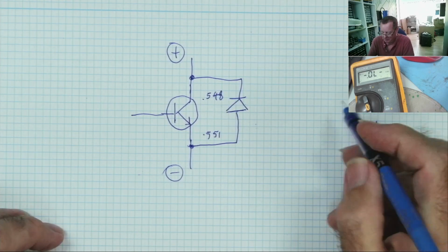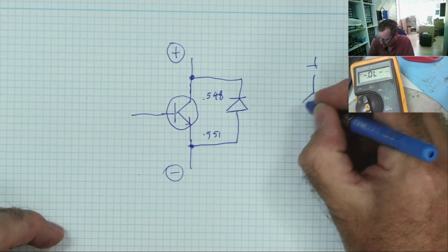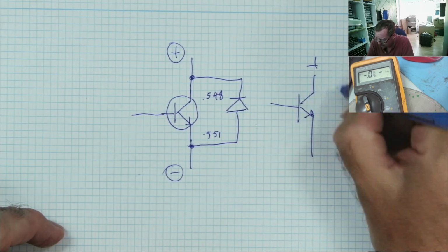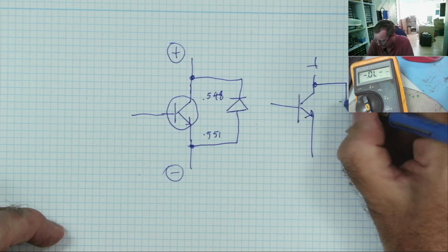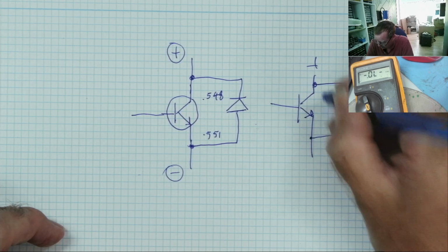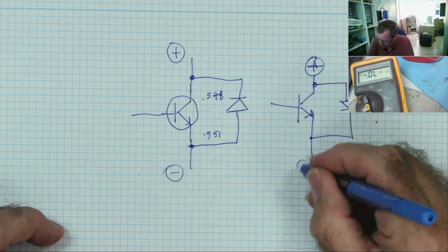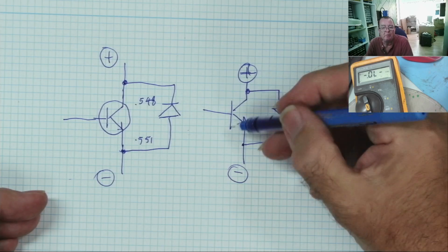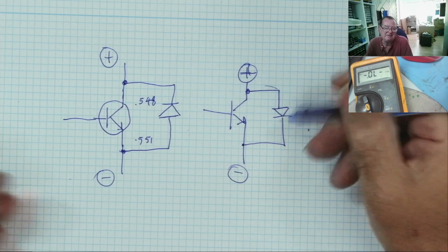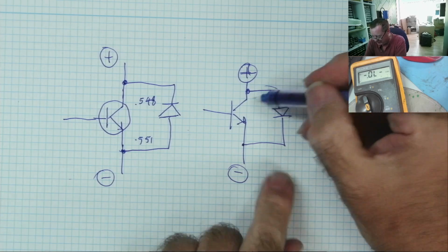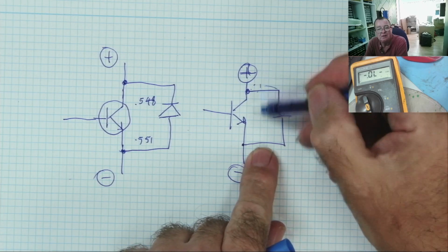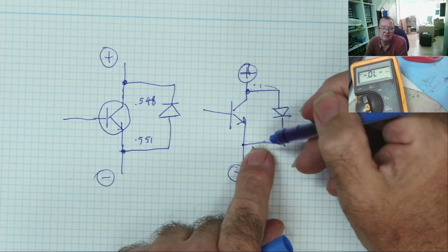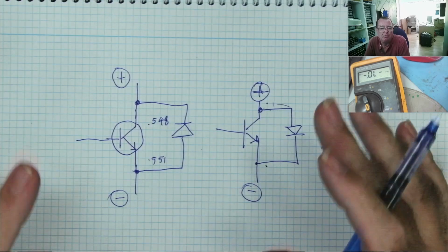It's not a problem. If I find the same thing, and you know it's just the opposite of what I've drawn, and I find what effectively looks like a diode going that way, collector emitter, and it's NPN. This end must be positive with respect to this end. Why am I seeing a diode junction here? Because effectively that means that the voltage on here cannot be more than 0.5 volts, or 0.15 for Schottky, than the voltage on that end, and that is not normal.